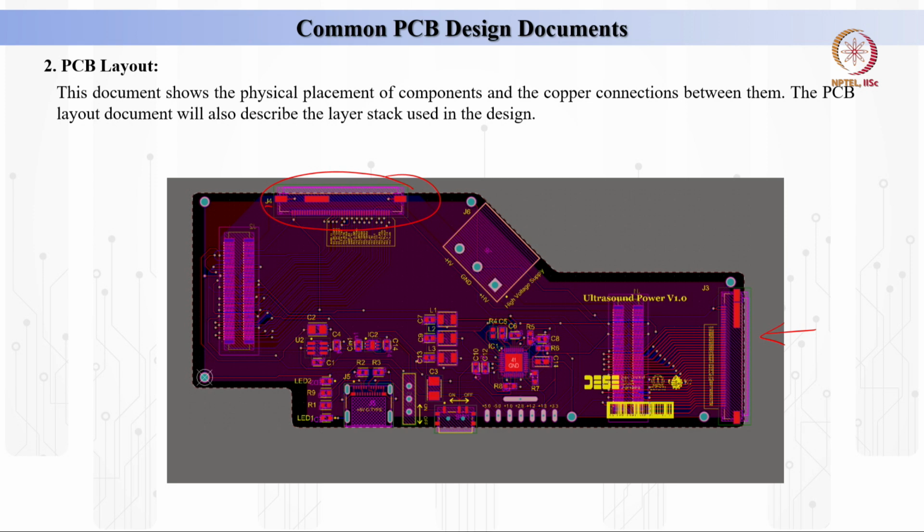Now here we make physical connections. Unlike nets, here we have to physically connect the components together using something called tracks. So these are called tracks. The individual lines that you see on the right in simple red colored lines, these are called tracks. All the items colored in red are in the top layer in this particular design software, and all the items colored in blue, which you may or may not be able to see, are in the bottom layer.